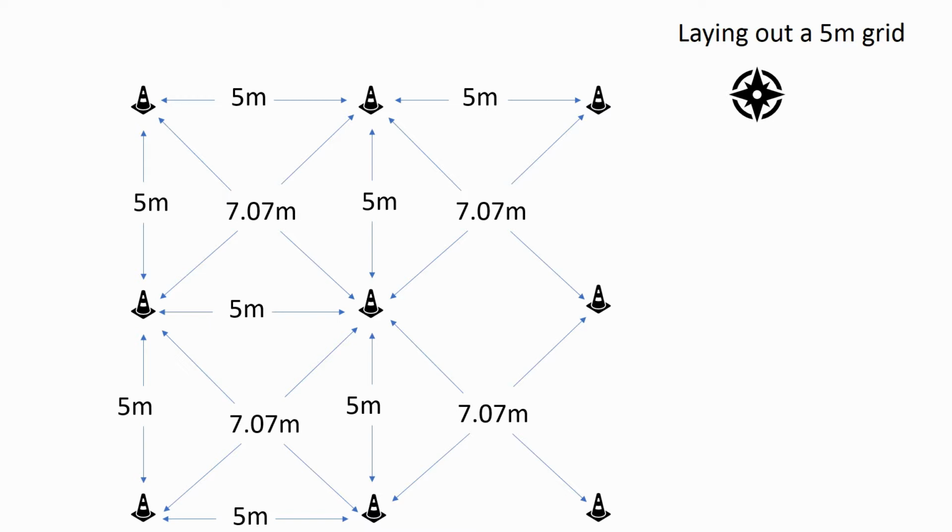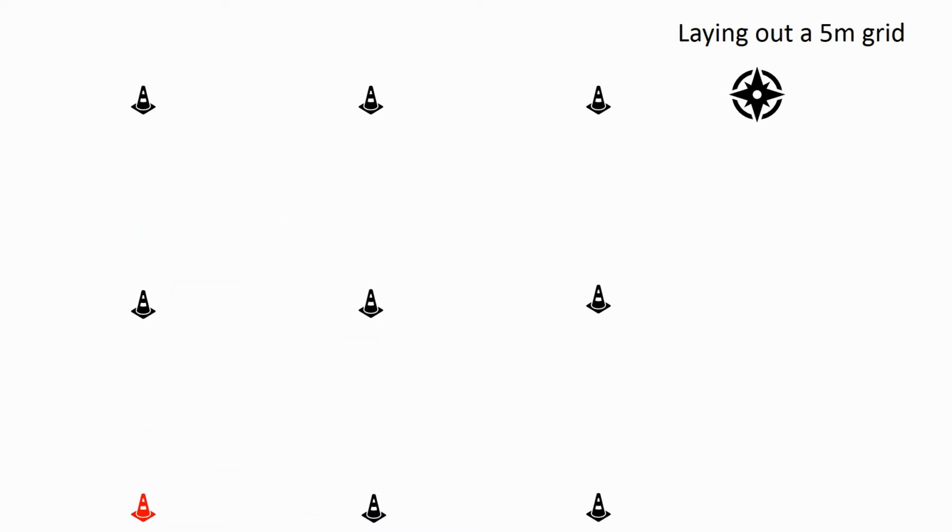Because you'll be creating a site or local grid, you will need to give an origin point. This is the bottom left corner, or in this case the southwest corner. You'll need to give this a coordinate. It's tempting to start with 0 meters east and 0 meters north, as this looks the easiest way to remember coordinates. Don't. If you extend to the south or west in this case, then you'll end up with negative numbers. Consider using coordinates that will leave plenty of room for expanding into these areas.